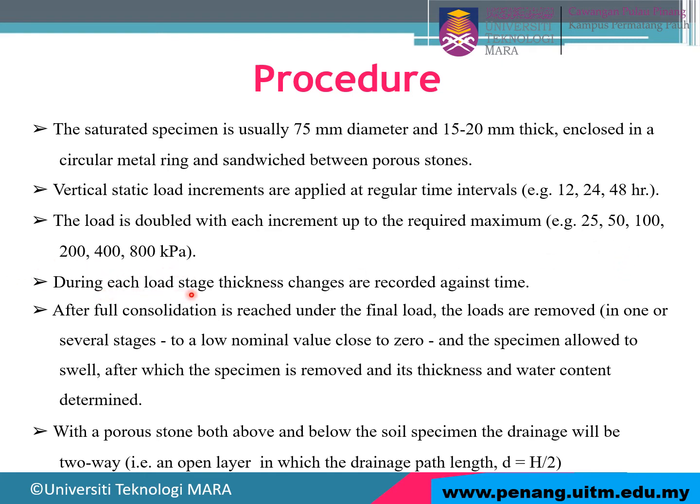During each stage, thickness changes are recorded against time. So we record the thickness. After full consolidation is reached under the final load, the load is removed in one or several stages to a low nominal value close to zero. The specimen is allowed to swell, after which the specimen is removed. Thickness and water content are determined.